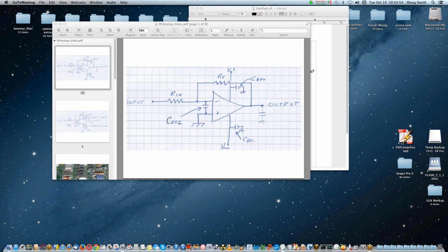I wouldn't consider myself an expert on shielding, but I think that any shield is going to be a problem because you've got to get the signals in and out of it, and it's not going to be complete, right? It's not going to be perfect. So, I guess the techniques that you're talking about here, putting decoupling caps, is probably one of the best things you can do. So, rather than trying to brute force shield it, just try to handle it locally.